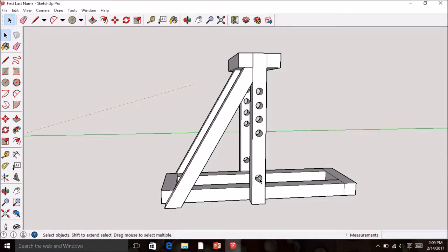We'll end up having 2 dowels. There's going to be one down here that holds the rubber band, another one over here that ends up being for our adjustable arm. And we're going to be able to adjust the height of our arm. We're also going to be able to adjust the length of our arm because we're going to have these variable holes that are drilled. So just because you're building the same catapult as your partner, you might decide for a little less power or a little more power and adjust your length and your angle.